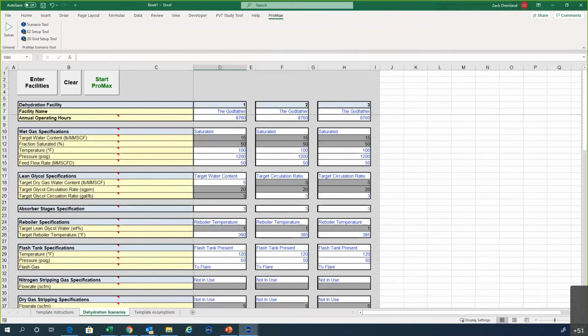Okay, so someone also mentioned that there's a rule of thumb for gas absorption and TEG from GPSA, and that's about 0.5 to 0.6 standard cubic feet per gallon of glycol. Okay, I'm unfamiliar with that specific rule of thumb. Is that for all hydrocarbons, or is that for BTEX? I know that GPSA specifically has something that the breakdown of what the BTEX pickup will be, but I wasn't sure if they had something for all hydrocarbons there.